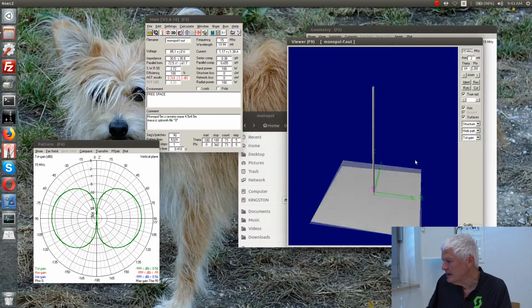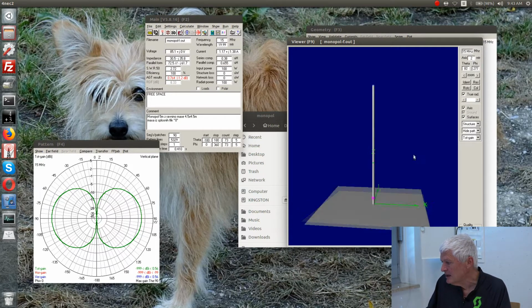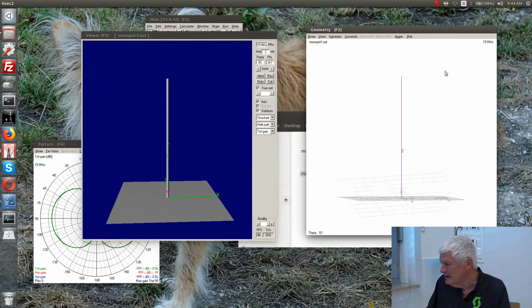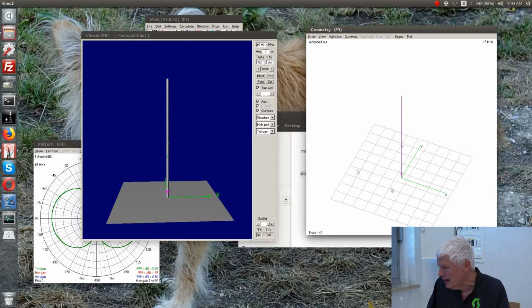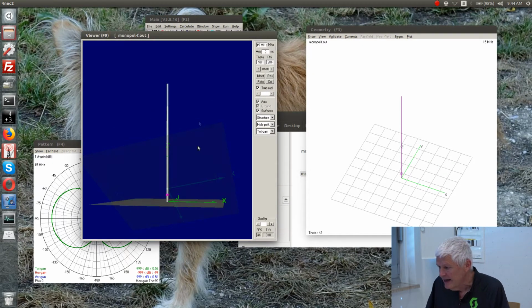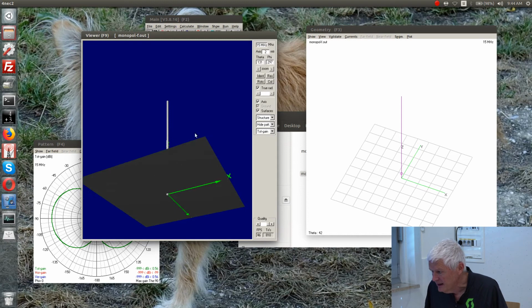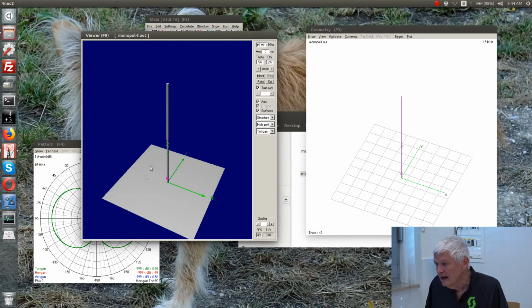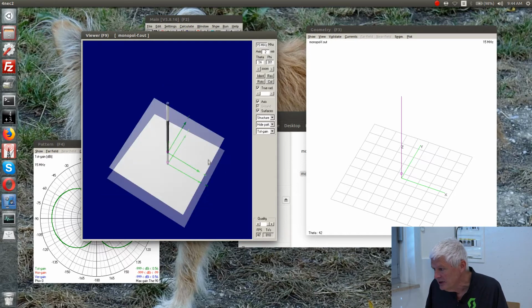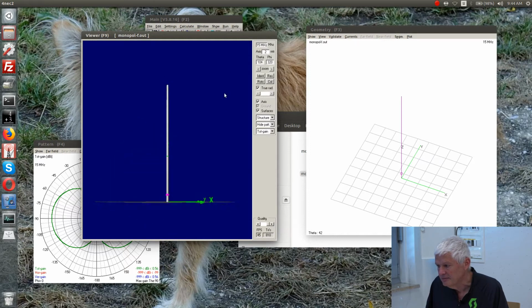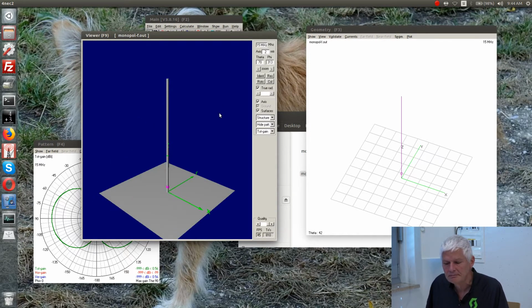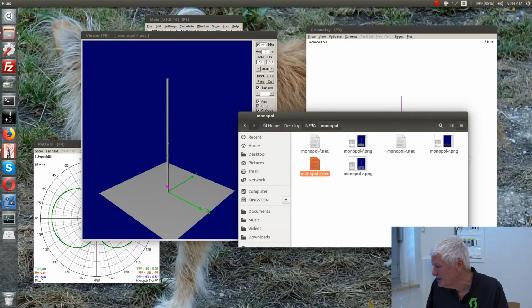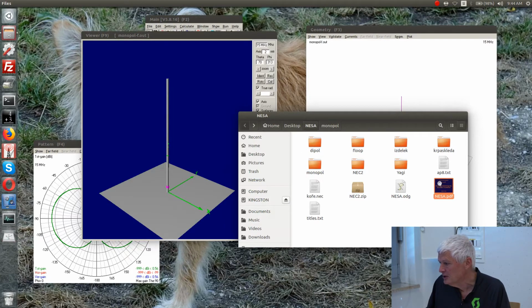You see now I have the surface made from patches. Now the patches are shown in quite a different way here. This is the same picture, but these are patches. They are no longer wires, as they are shown here. They are shown as patches, and patches have an inner surface and an outer surface. Currents are only allowed to flow in the outer surface, not in the inner surface. This is non-physical. I stressed this in my presentation here. If I open just the presentation here.